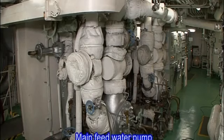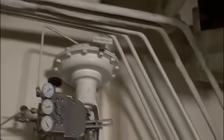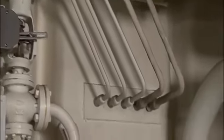Take samples of feed and boiler water from operating boilers at least once every 2 days. Use these samples to determine the condition of feed and boiler water. When necessary, take proper measures to address water quality issues.